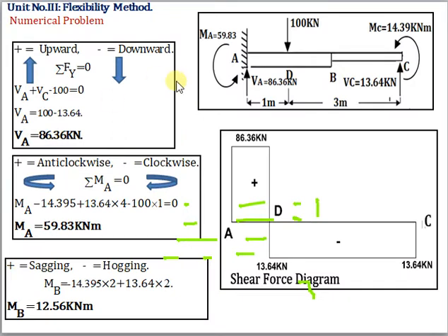Now we know the redundant forces. Now let's consider the released structure and apply the known forces. Now let's find the other unknowns. The structure is now determinate, so let us use summation Fy, where upward is plus and downward is minus.